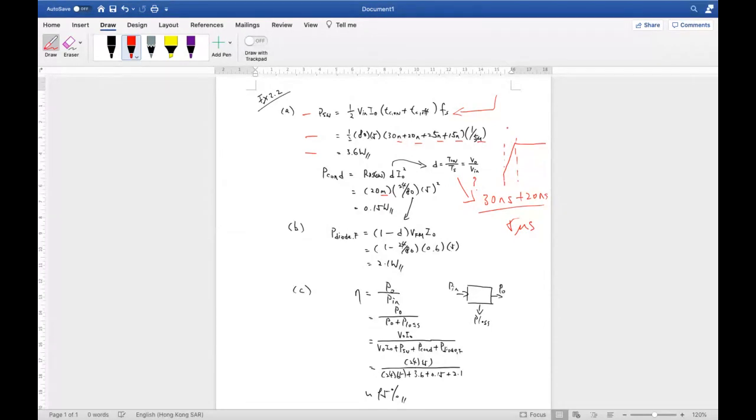So here is the switching on, switching, and here is the on interval. It's different, right? So here may be the turning on time, and this definition should not be the same as the on interval. This on interval is, after switching steady, the period of time when the MOSFET is on. And here, much shorter, the nanosecond, is the switching on or off interval. So we cannot do it like this.